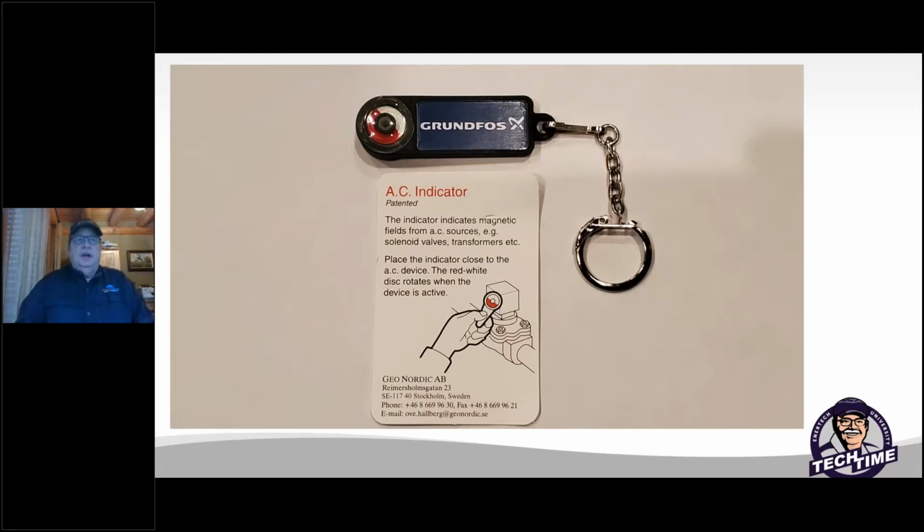One other thing I wanted to bring up today is this little tool a lot of you guys have probably seen or passed out. This one is sponsored by Grundfos. It's a power indicator, AC indicator, where you can put it up to the circulator pump and see if it's spinning. That's supposed to tell you if that pump is actually running. But I want you to remember that these motors are impedance protected, so there's still electricity going through them. They may not be running, but they're still going to be drawing electricity. And so this can give you a false reading. If you had a shaft break inside the pump, this could still show you that something is spinning, but the shaft is broken. So don't always trust these 100%.